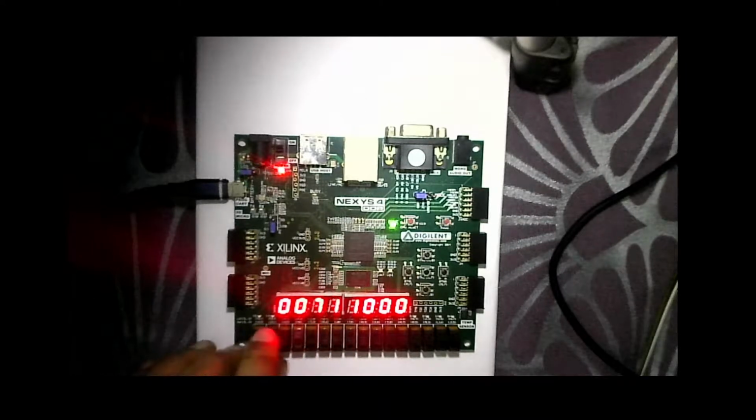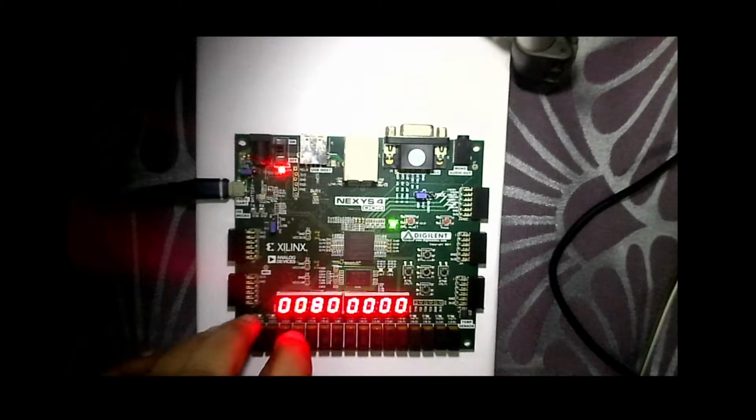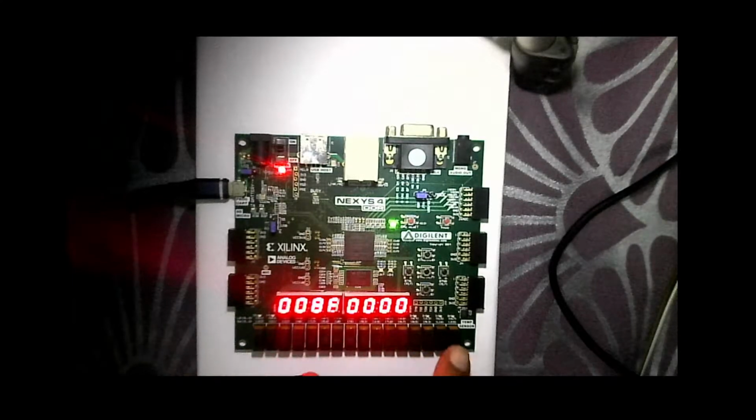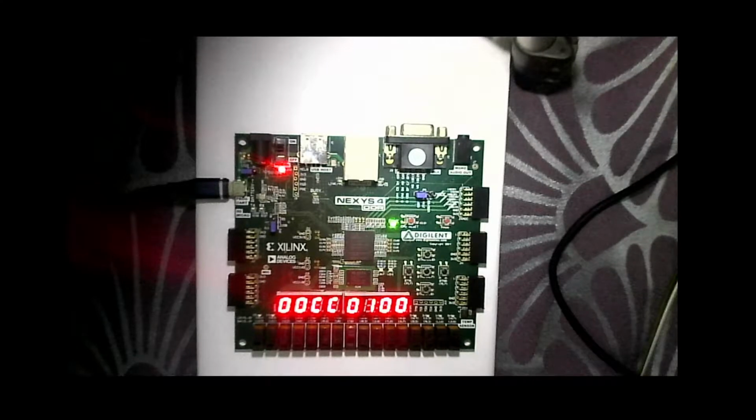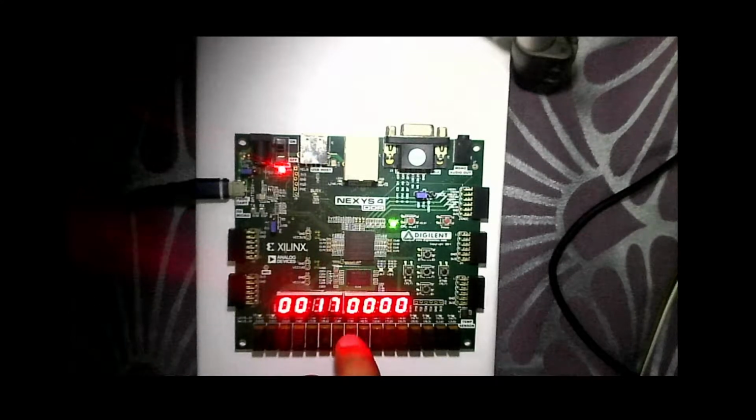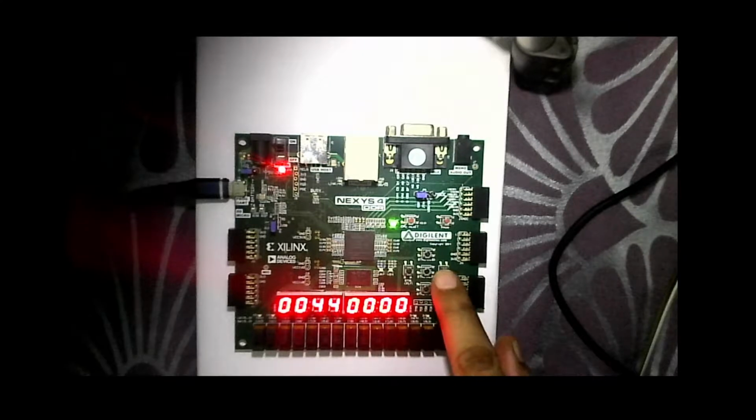Now if I want, I can choose a smaller number. Let's say this is 4, this is 4, and this one. So let's say as soon as it becomes 100, it should reset. So it will become FF, and as soon as it becomes FF, it is going to reset. It got reset. So you understood that I can feed in any number. At this point, of course, it is counting because that state will never compare unless it goes all the way around to 0 0.